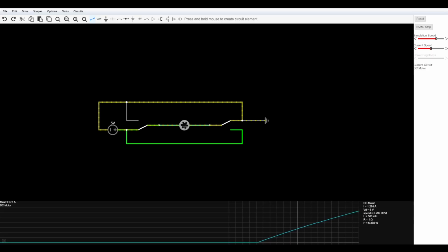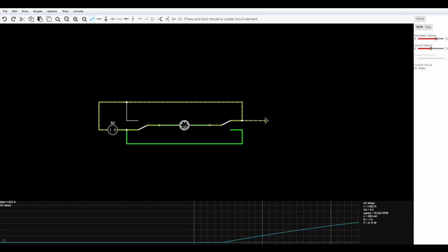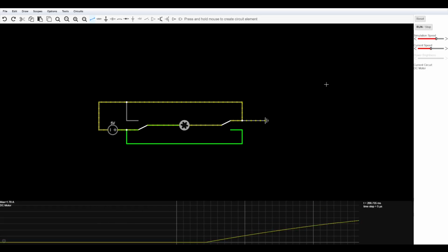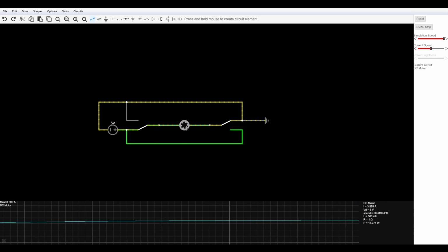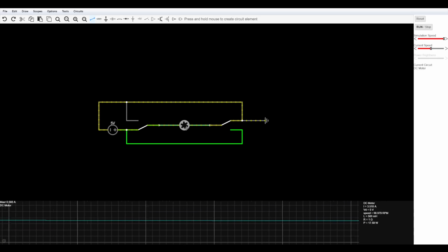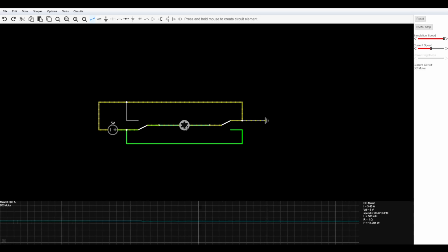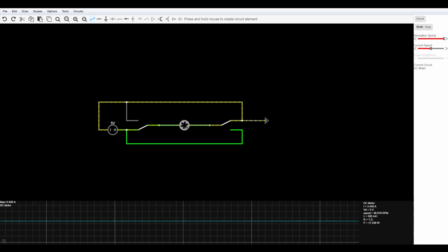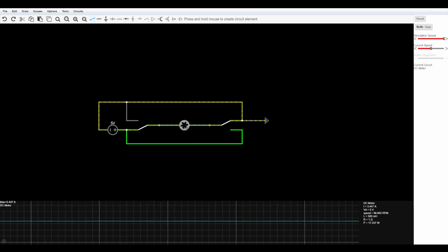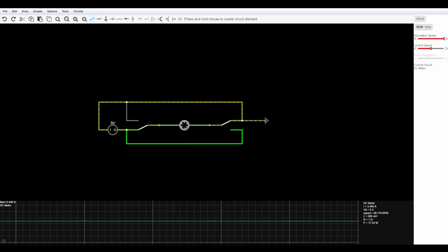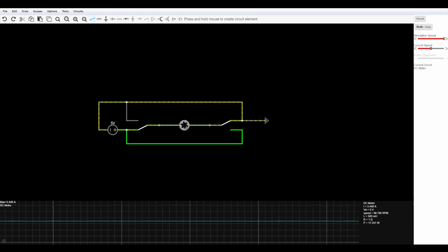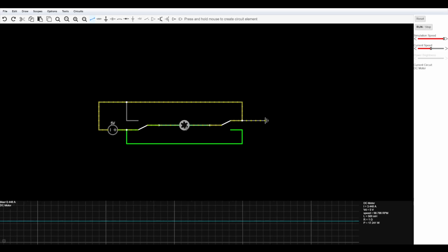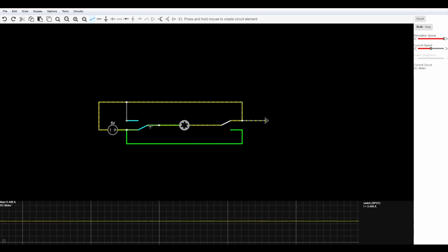So it's well above 1 amp at this point. It keeps climbing. RPMs are going up. Now, this is kind of slow, well, let's speed it up a little bit. Okay, it hit 3.5 and it's kind of easing off there. It's hovering around 99 RPMs, but yeah, 3.4 amps at 5 volts, doing 17.2 watts of power.